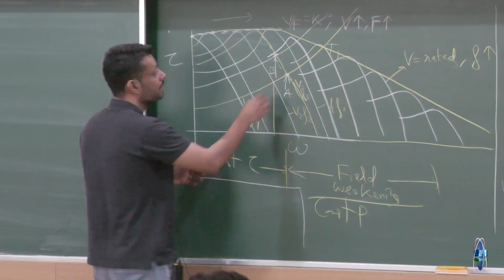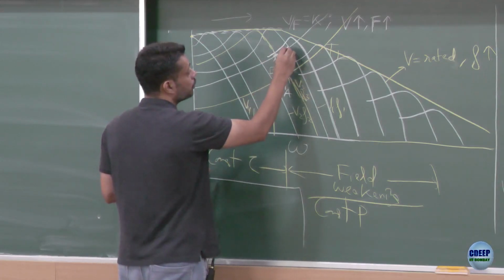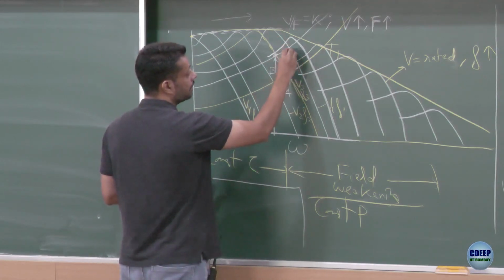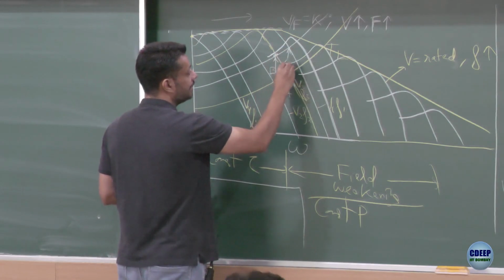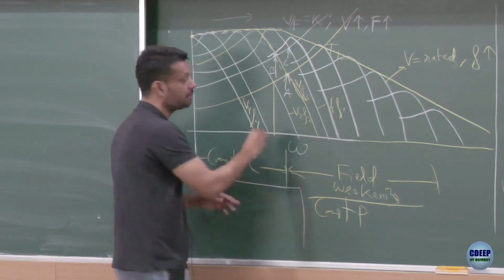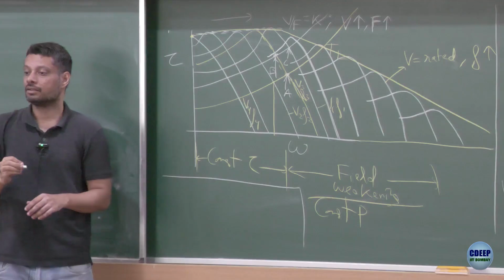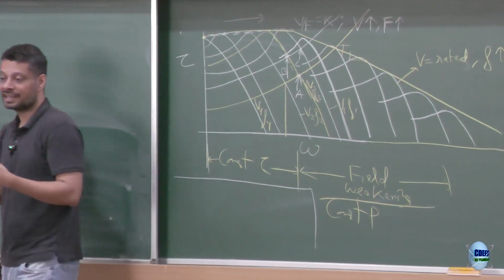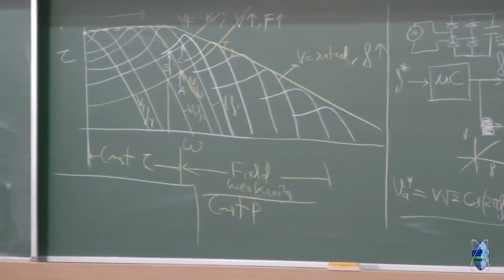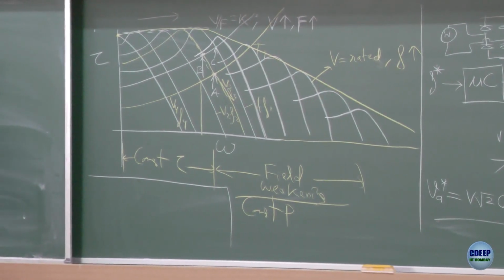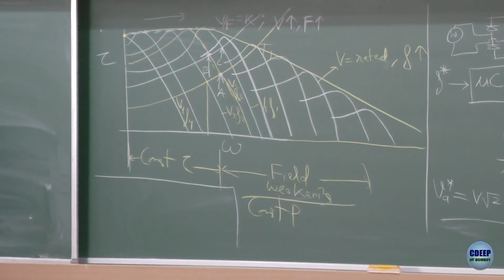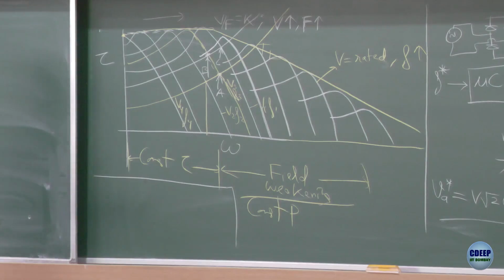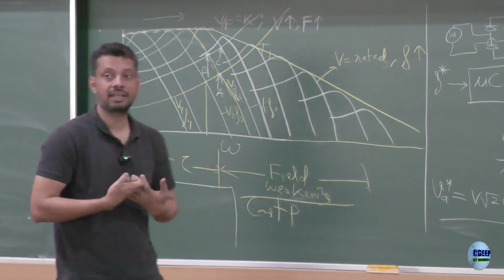If you increase the frequency a little bit more, you would go to this characteristics, the new one, right? And you would move to point C. Point C and point A, same speed, right? So if you have some mechanism of actually observing the speed, then you can always build a small logic, and write a small code in the microcontroller to adjust the frequency so that you are always operating at the same speed. Is that okay? Should I repeat once again?